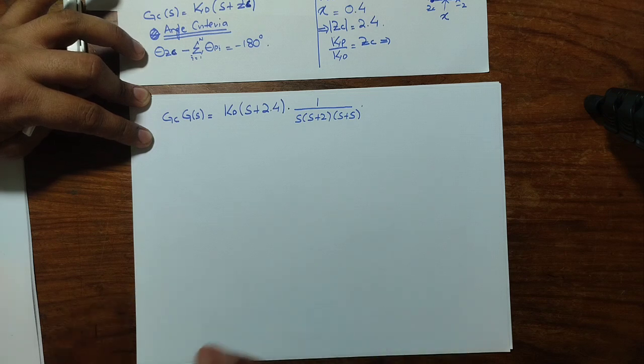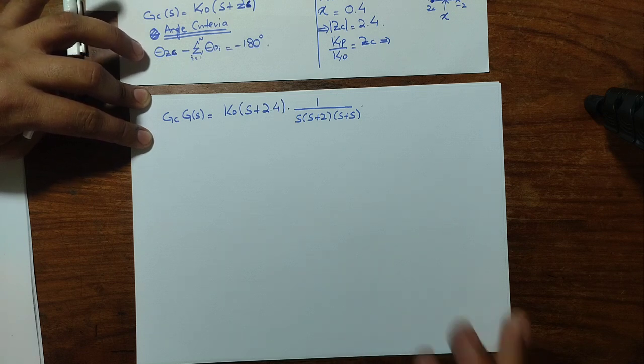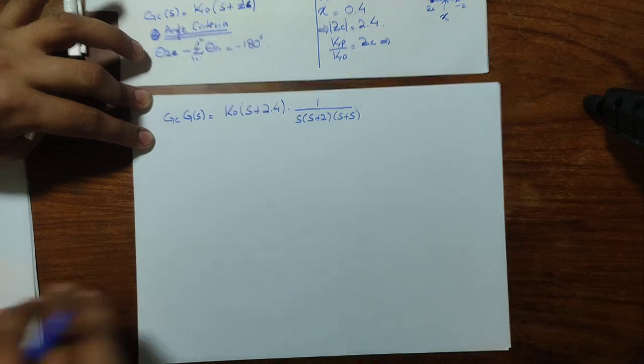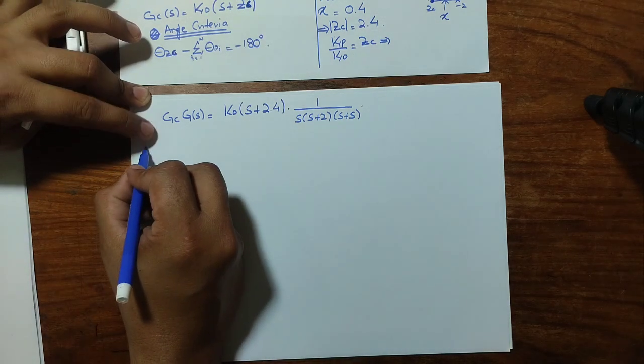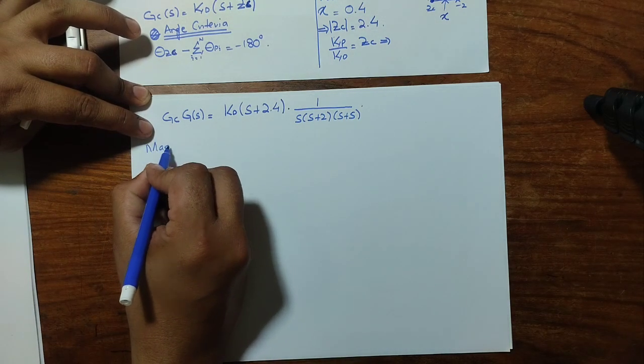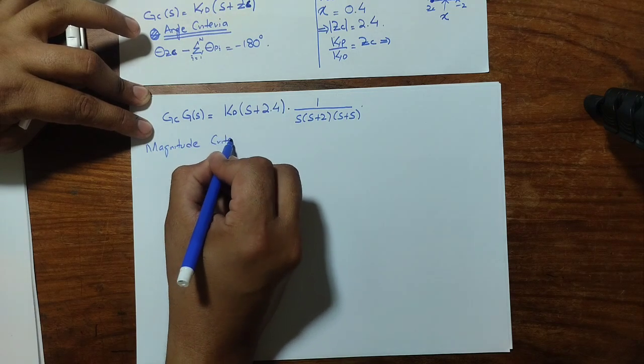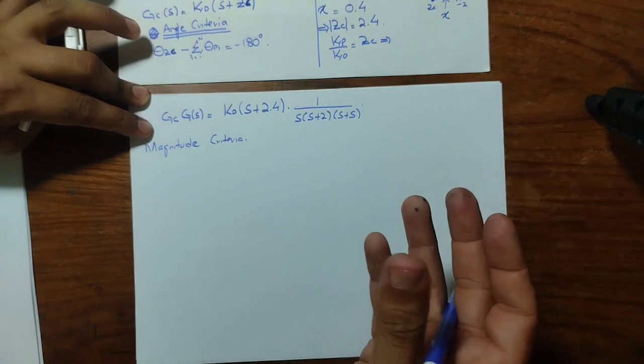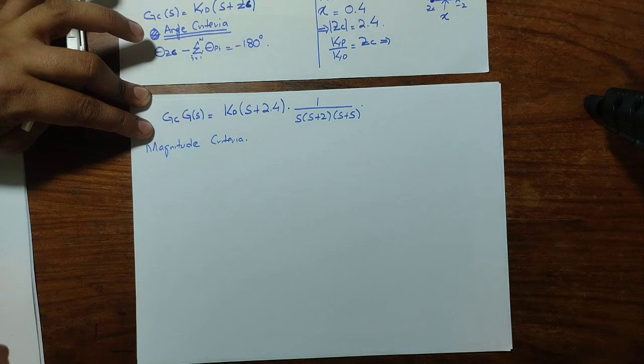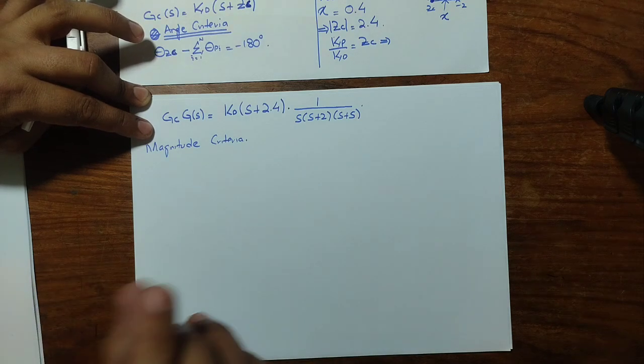So now we have to find the gain that is required to achieve this desired point, these desired specifications. If those gains are real, it implies that the root locus will pass through the desired point with this kind of controller. So again, following the magnitude criteria that we normally use in root locus design, that implies the contribution of each pole and zero towards that desired point.